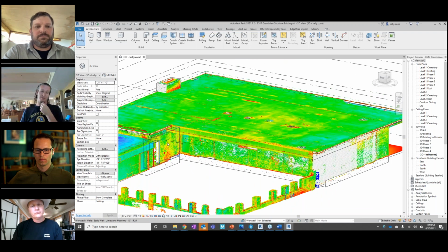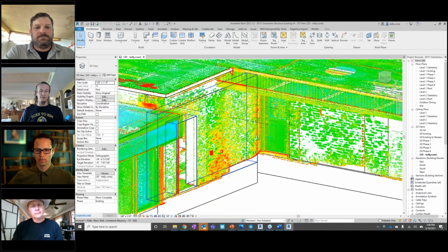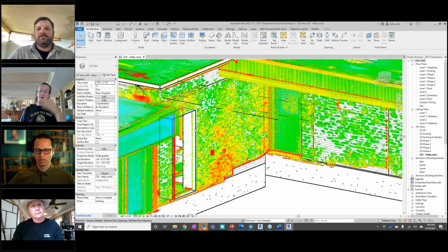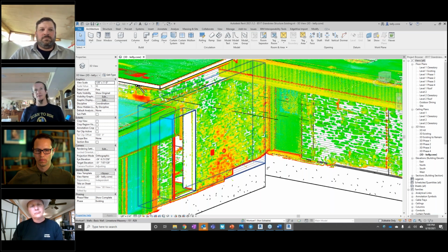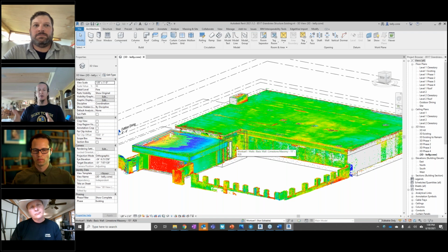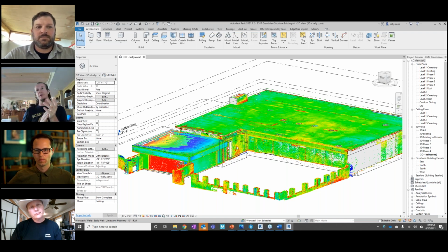This also tells you interesting things about texture. This is a rough ashlar wall, so the stones here are out, the stones there are in, the grout is inboard of that wall. This also gives you an element-by-element breakdown inside of the Verity software, where it'll actually show you, for each wall, how much it's out as an average to those points.